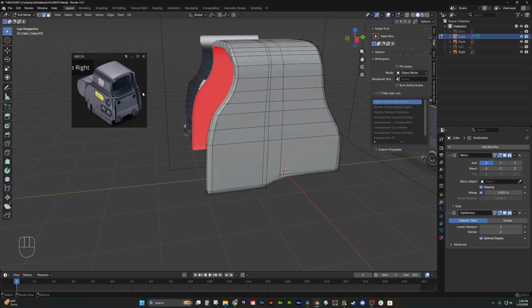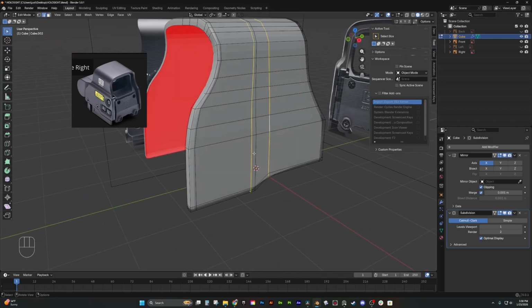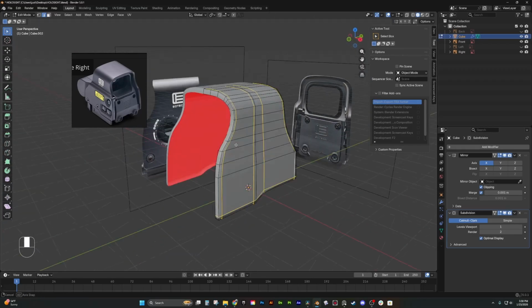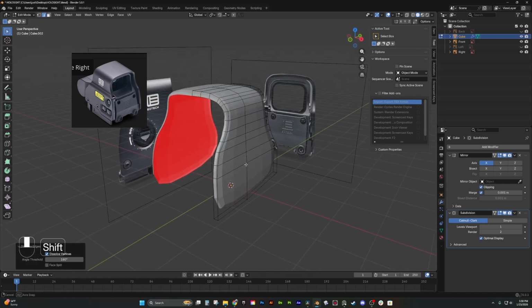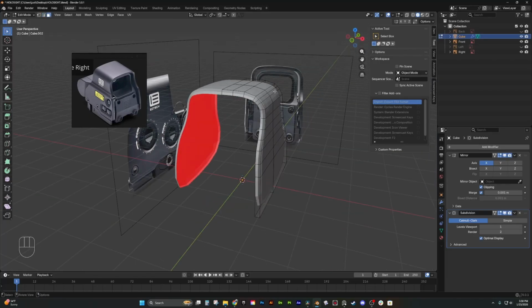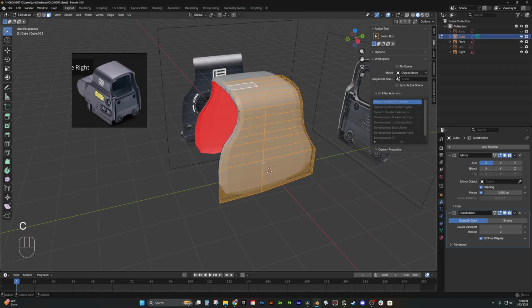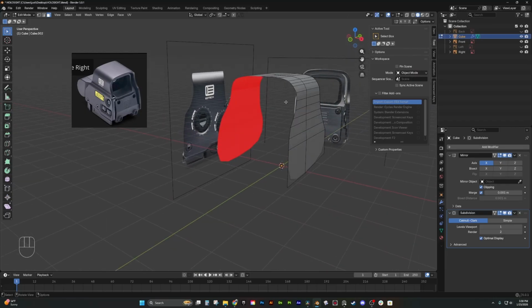So we're going to make this a little bit easier on us, and for now, I'll delete the extra edge loops that we've done. This was more to see if our final version would smooth correctly, and it does. I've used Alt-click to select them. I'm going to dissolve these edges so they're gone now. Because what I want to do is grab perhaps actually just these faces, and I'll press Command I to invert that and delete these, because I want the entire face to be thick.